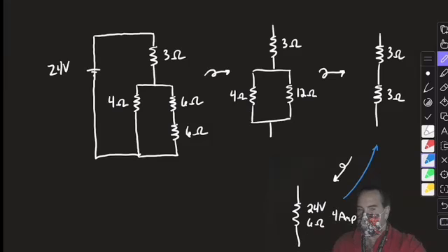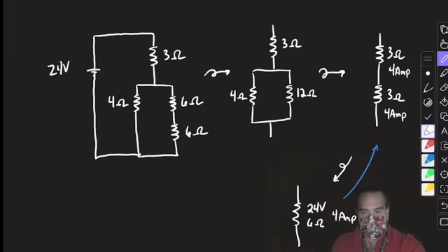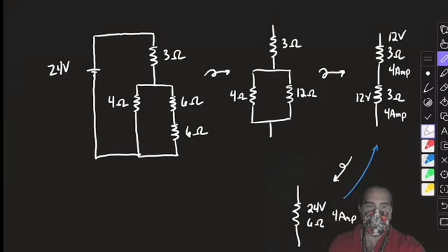So if I step backwards and I'm going back to a series circuit, I'm going to apply the current to each element that is in series. Because there's no breaks in the circuit, each element must have the same current. Once I've done that, I ignore the simpler circuit and I focus on my new circuit, using Ohm's law again to figure out the voltage for each of the elements in the new circuit. In this case, 12 volts and 12 volts. V equals IR.